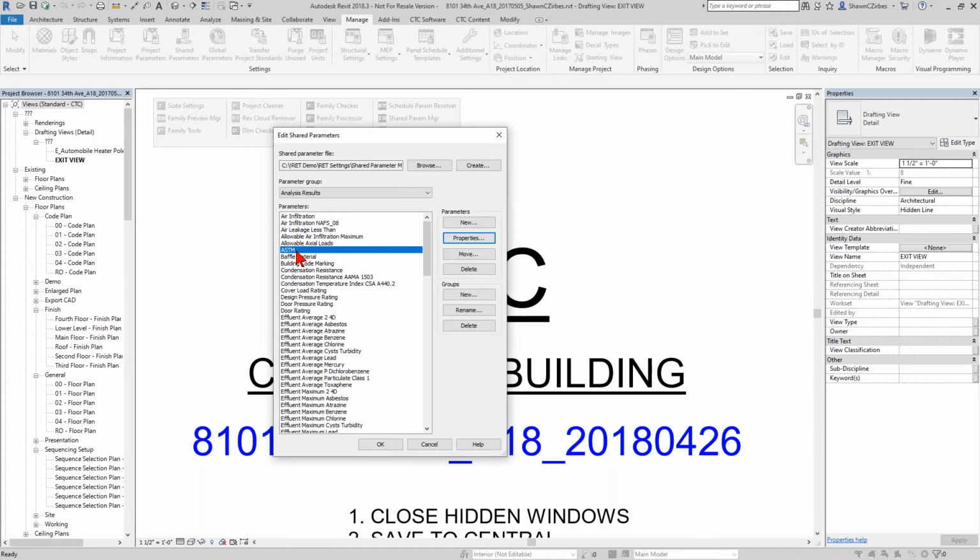And if you were to go to the text file and edit it manually, you actually run a pretty high risk of causing problems in Revit if more than one version of the same shared parameter makes it into a project model. You can actually crash Revit to the desktop with no option to save in a lot of cases. Not all cases, but a lot of cases. And so that can be really dangerous for working with those shared parameter files in a text editor.